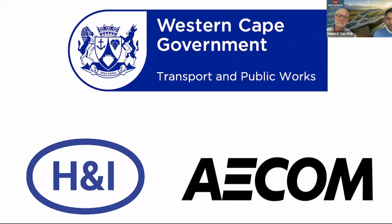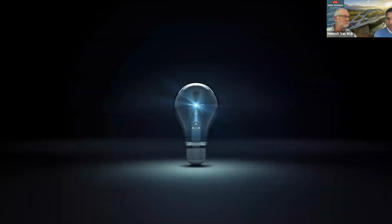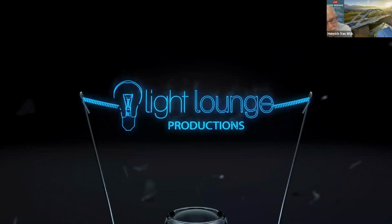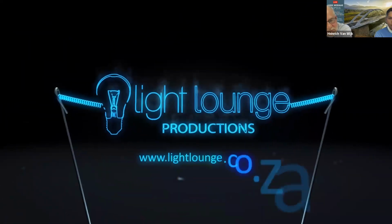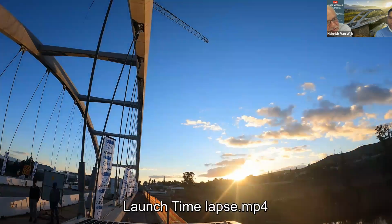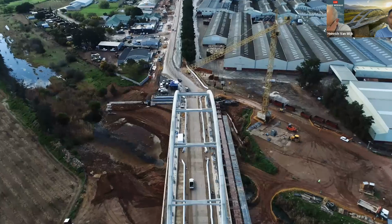Okay, so for the first question, when you say tensioning, for the post-tensioning, I'd have to check the numbers, but it's about 30 odd MPa. We also have a minimum time limit of about 21 days. Yes, to limit early creep. That's right.